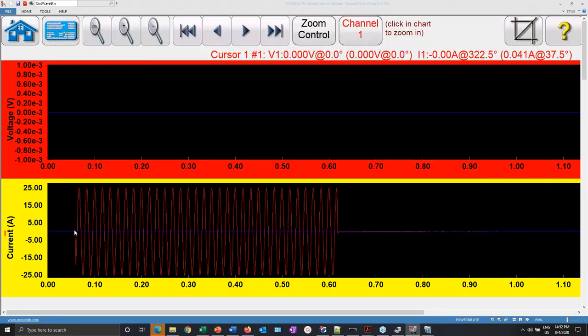When I'm using the overcurrent timing screen, there is no pre-fault, or I chose not to inject any pre-fault, and therefore there is no time between the moment of the injection and the injection of the full amount of current for that fault. Why do I say all that? Because that is going to change the behavior of the relay a little bit.